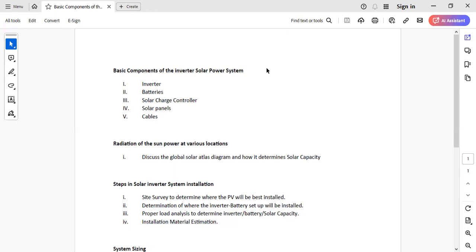In the telecom sites, there are hybrid sites where diesel is to be conserved. When these generators run for a particular time, they charge the battery and shut down. Then the generator rests, then solar, and the battery will power the site for a period of time. When the battery reaches a particular level, the generator will start automatically. These things are not too complicated. They are simply an arrangement of cells to achieve either high voltage or high current, depending on how you want it.